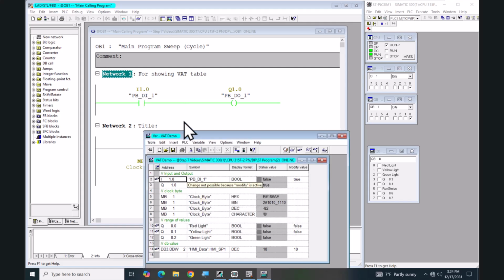In this case, you will see the value updated in logic, and you will also see that in PLC Sim. So this value, you could say, is being written in between the card being read and the value being put into the process image input table. So that's why you see this input value showing up in logic.